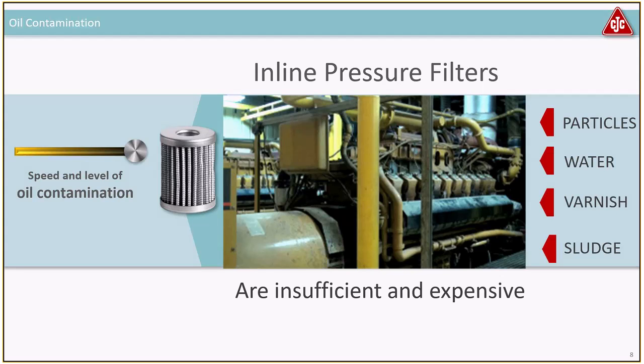If you have a very good quality and very fine inline filter, it could be very expensive to run. If you have a turbine, for example, with a 3 or 5 micron inline pressure filter, they are typically very big and quite expensive. So you could do it in a different way, and we'll go back to that, combining more types of filters.